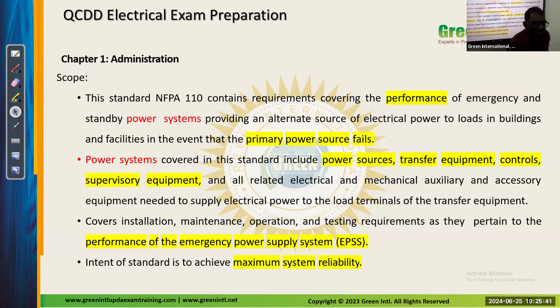Primary power failure can happen in this building, in a hospital, and in data centers. But we need to categorize into 3 different categories. In a normal building, on power failure we need a backup power, but not immediately. But in a hospital, we need backup power immediately. So we need to categorize the requirement, which is another important thing. We categorize based on the level.